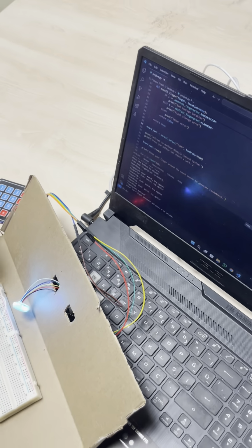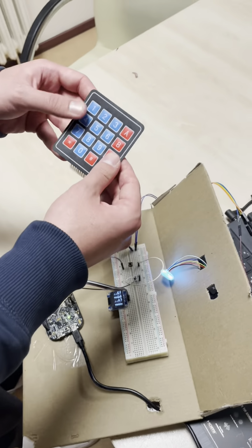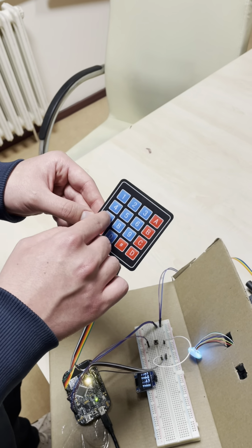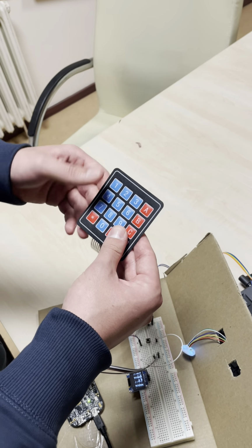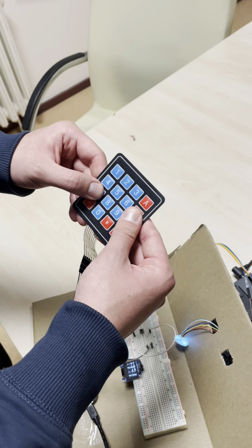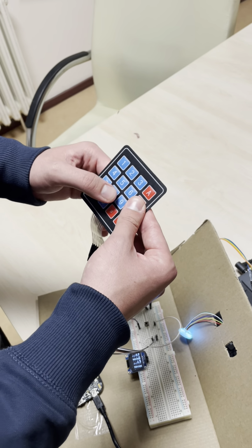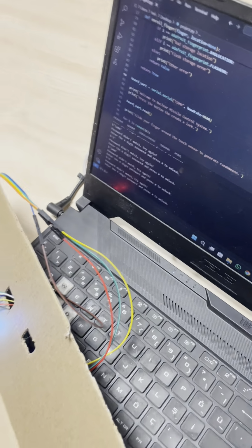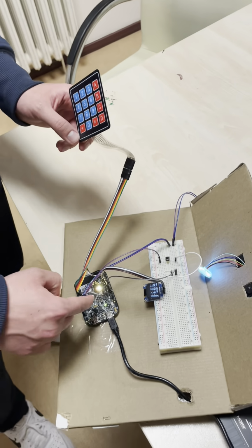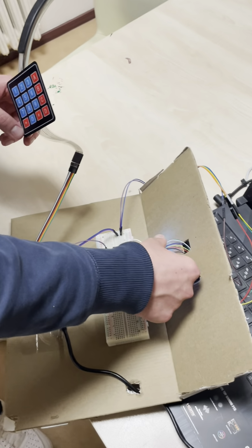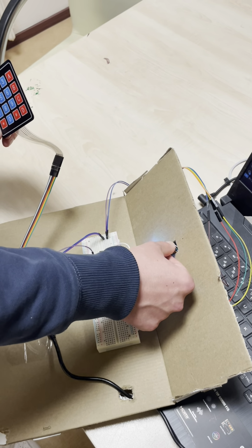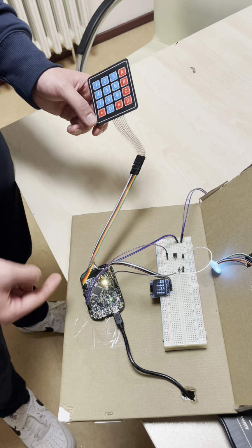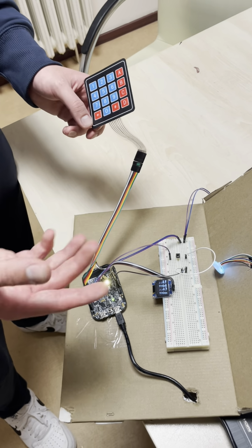Enter the 4-digit password and press hashtag to unlock. Now I get the keypad and we set the 7777 password. Now I will try a wrong password. For example, 7779, and I press this. As it can be seen, it says password didn't match. Try again. By the way, we are in the half of the authentication. We activated the first step with our fingerprint and the LED turned yellow. It was red before the fingerprint match.